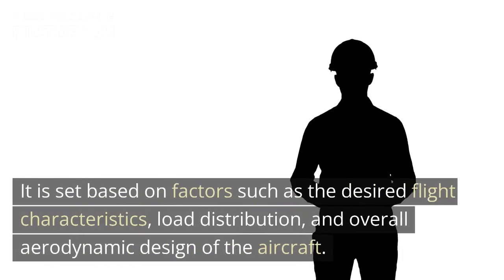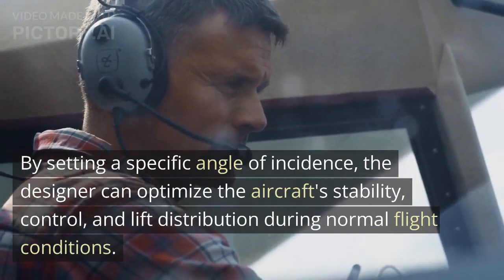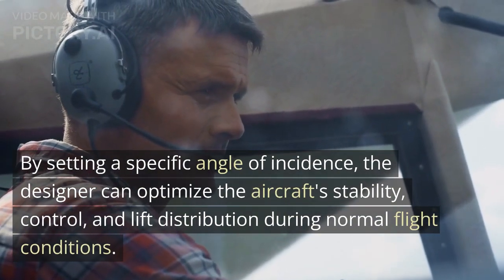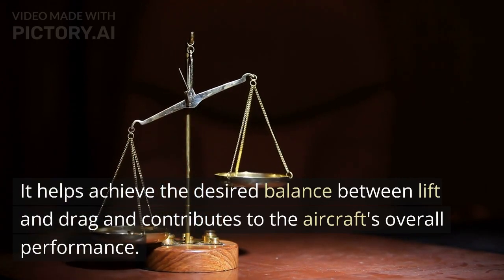It is set based on factors such as the desired flight characteristics, load distribution, and overall aerodynamic design of the aircraft. The angle of incidence is typically positive, meaning that the wing is slightly inclined upwards relative to the longitudinal axis of the aircraft. By setting a specific angle of incidence, the designer can optimize the aircraft's stability, control, and lift distribution during normal flight conditions. It helps achieve the desired balance between lift and drag and contributes to the aircraft's overall performance.